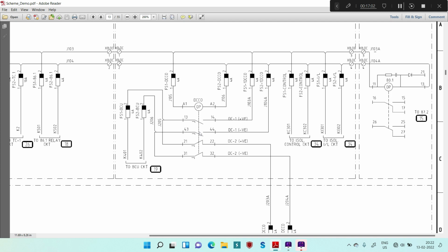All the electrical scheme drawings are generally made with the assumption that your lines or your feeders are in shutdown condition. So all the drawings are with de-energized conditions only. So all the contactors are with de-energized conditions. All the auxiliary relays are with reset conditions.